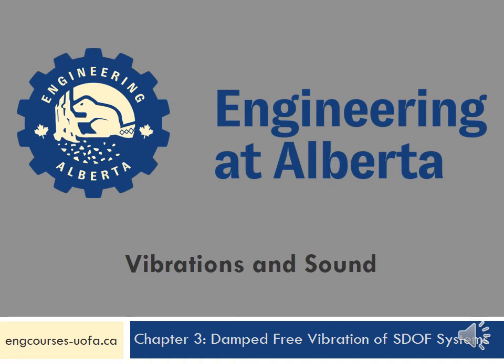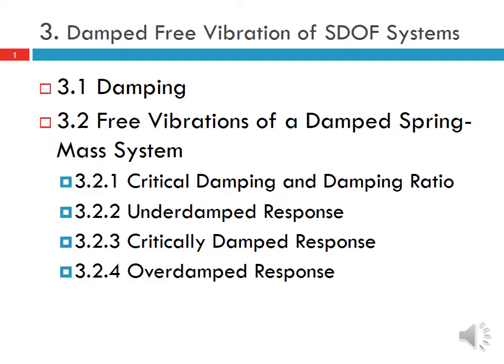In this video, we're going to discuss Chapter 3, Damped Free Vibration of a Single Degree of Freedom System. So far, we've talked about undamped single degree of freedom systems undergoing free vibration. So here we're going to add damping. We're first going to talk about what damping is and the different forms it can take, and then discuss free vibrations of a damped spring mass system.